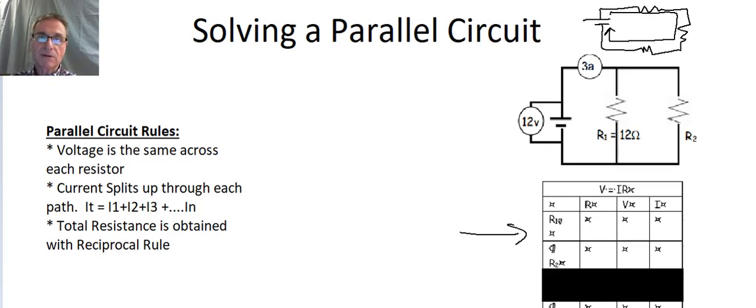In a parallel circuit, the thing that really defines a parallel circuit is if we look at the circuit below the one I just drew, the current that leaves the battery, which we call I total here, when it gets to this point right here, and we call this a junction point, it has an option. Some of the current can go down through this resistor down here, and then some of it can go through this resistor down here. So some can go through R1, and some will go through R2. It has options, okay? And that's the basic difference between a series circuit and a parallel circuit, or how to identify one.